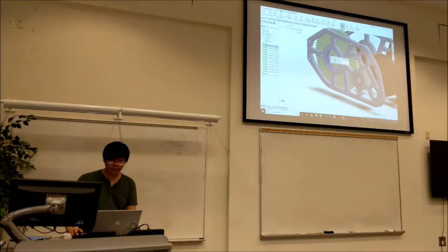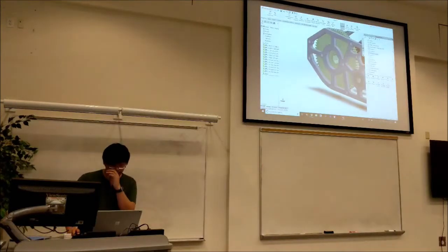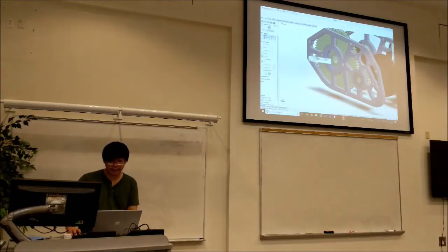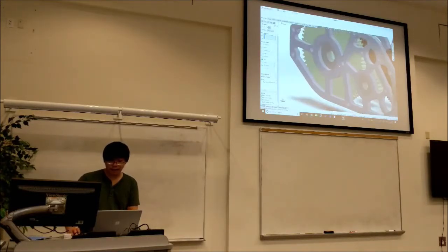Actually, we're missing a bearing here, so we can pull that in from the design library. So we're going to use the same shaft retention method. If we face the bearings inwards towards each other, then we can just use the shoulder of the hex to keep the shaft locked in place.